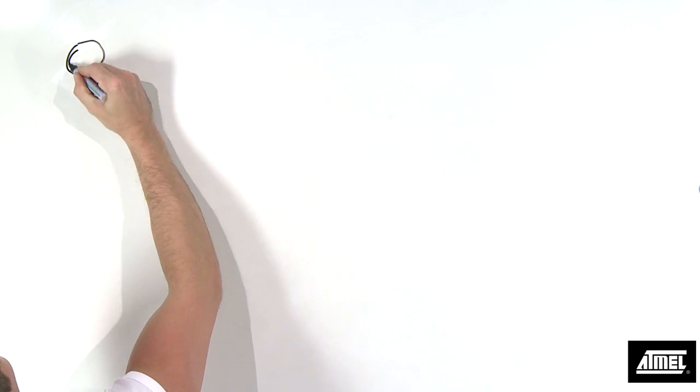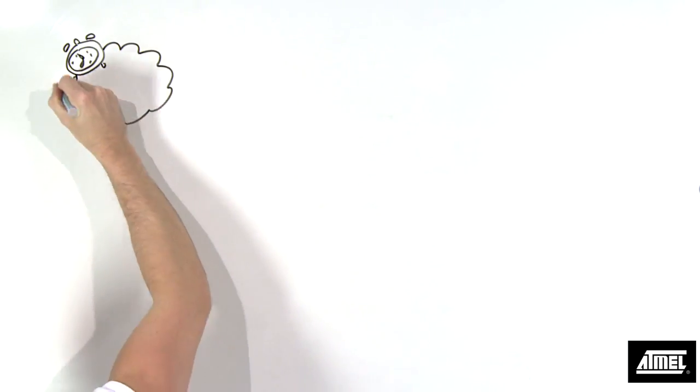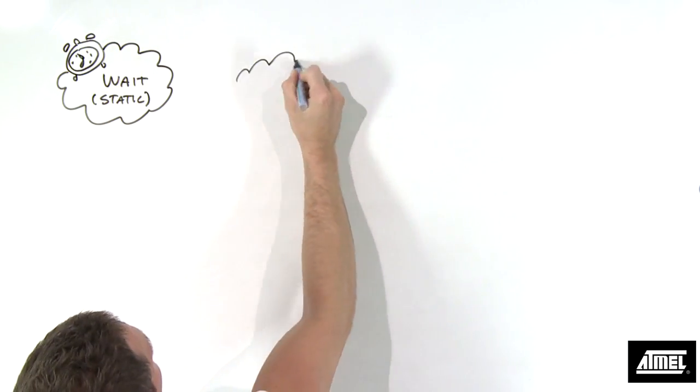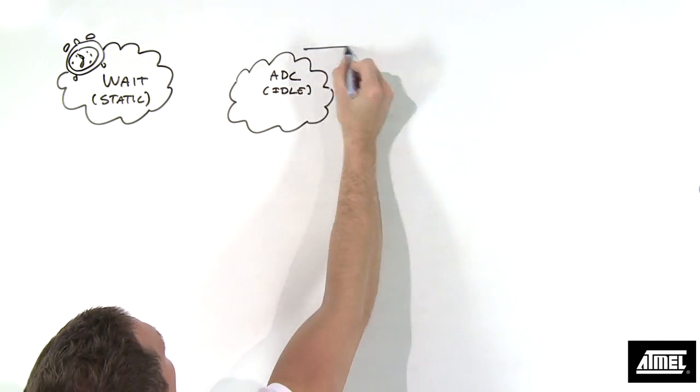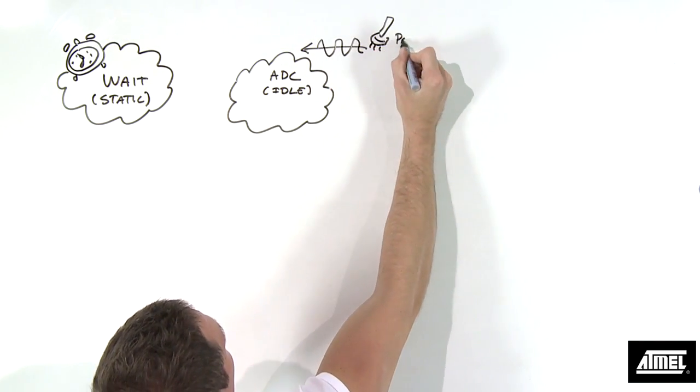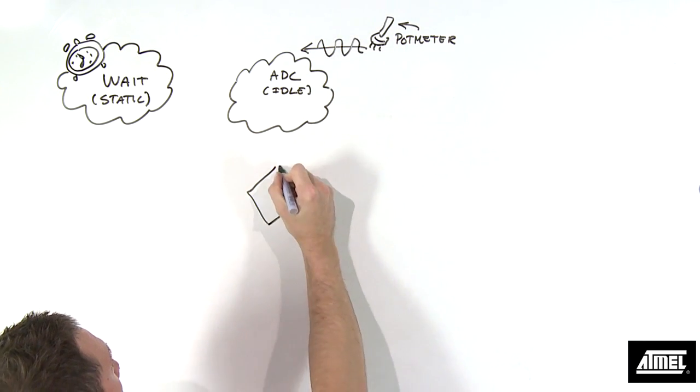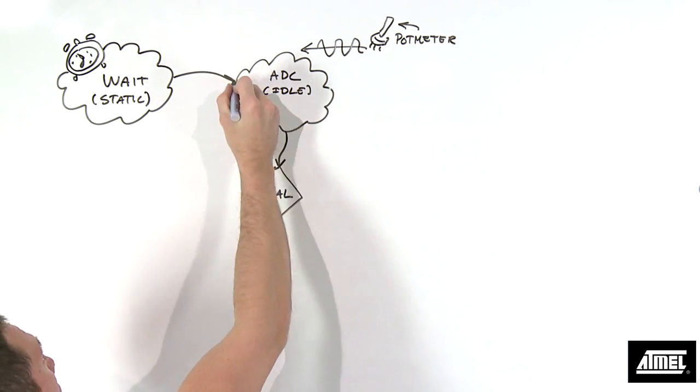In this video, we're going to use the sleepwalking feature of the AVR UC3L to save power without sacrificing functionality. Our example application is very simple and generic. We have an analog signal that we want to monitor. The moment the signal overruns a certain threshold, we want to increment the counter. For the example, we control the input signal with a pot meter.